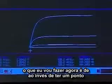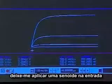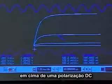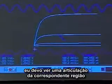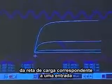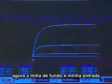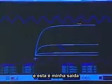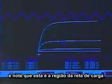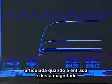Instead of having just a dot by having a DC voltage, let me apply an input sinusoid. If I apply an input sinusoid at some bias, then I should see an articulation of the corresponding region of the load line. As you can see here, the bottom line is my input, and this is my output. This is the region of the load line articulated when the input is of this magnitude.